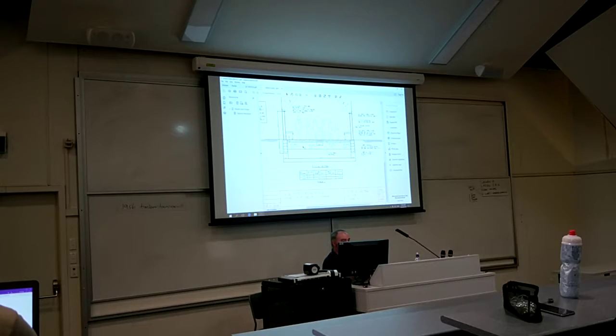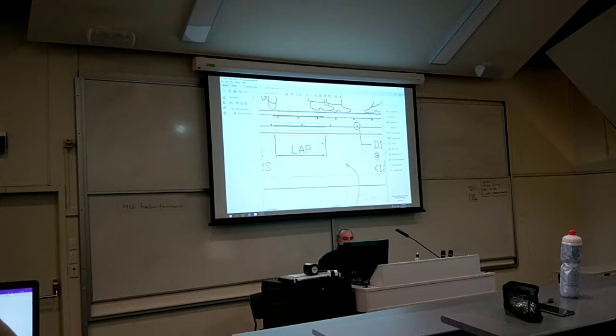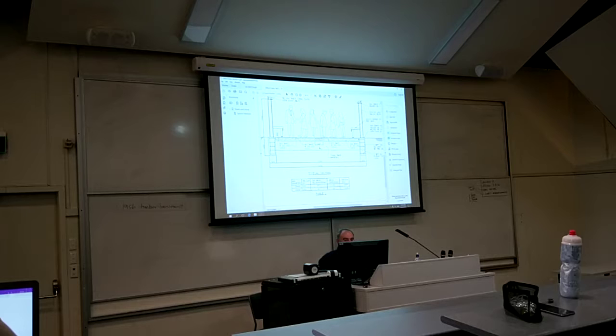It's important that you understand that this is very much a sketch, and exactly where your concrete should be to the outside edge. So you'll see that in a number of places. Where it says lap, okay, should be in the middle. Bang on in the middle. And you know what? If you do it in the middle, that means both bars either side will be exactly the same. So therefore you can only have to call up that bar once. But don't forget to count it as 2 each time.